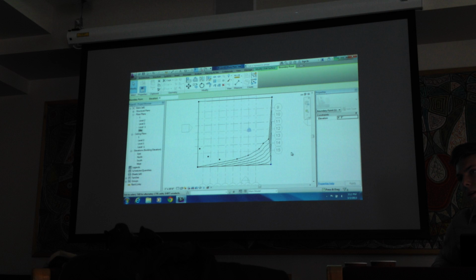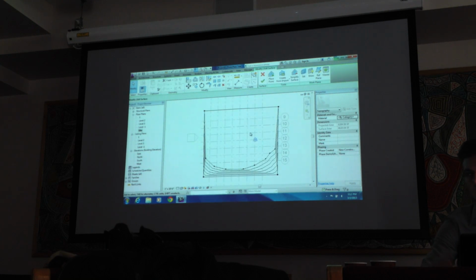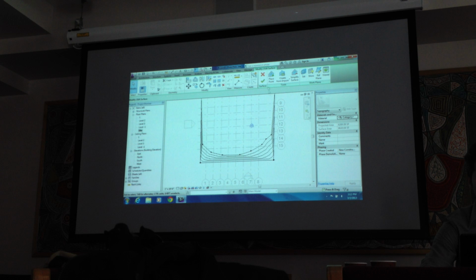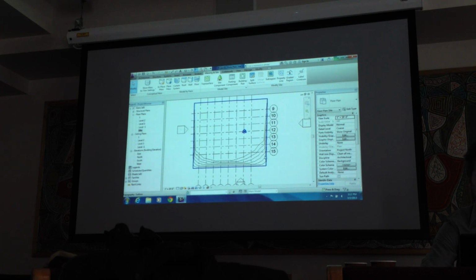And as you see, it will show a reference line for every increment. If it's in Imperial, it will be a different increment, and you can change these in the options category, which we'll go through later on. But right now, it's just showing 1 line per foot. So I'll change the other one to 6 feet as well. It'll create a boundary on where the flat plane is going to be and where a hill begins on the site that we're creating. When you're done creating the site, you just click the check mark to finish, and then the site will be created.